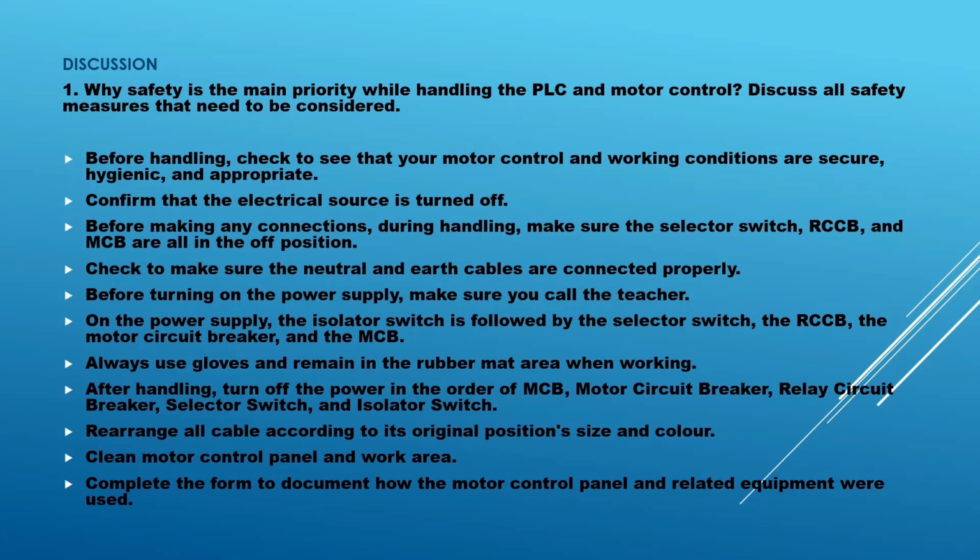Second, confirm that the electrical source is turned off. Number 3, before making any connection during handling, make sure the selector switch, RCCB and MCB are all in the off position. Check to make sure the neutral and earth cables are connected properly. Before turning on the power supply, make sure you call the teacher. On the power supply, the isolator switch is followed by the selector switch, the RCCB, the motor circuit breaker, and the MCB. Always use gloves and remain in the rubber mat area when working.